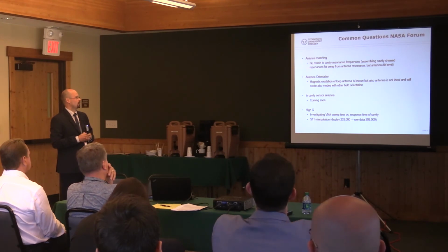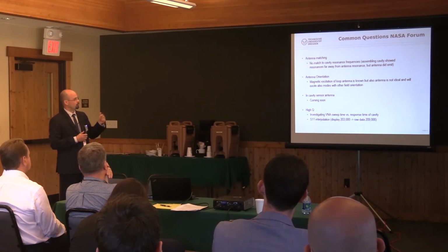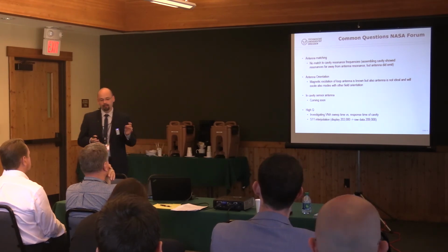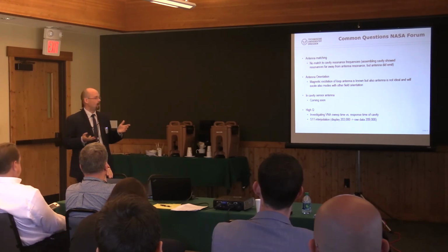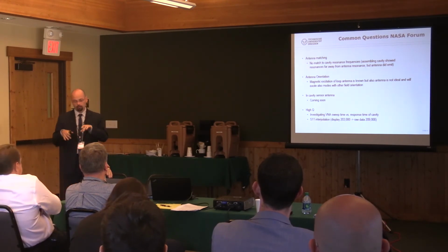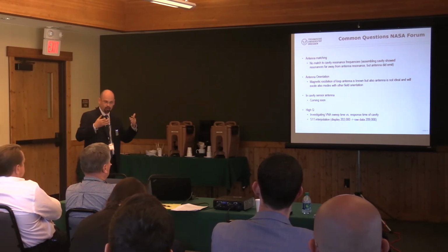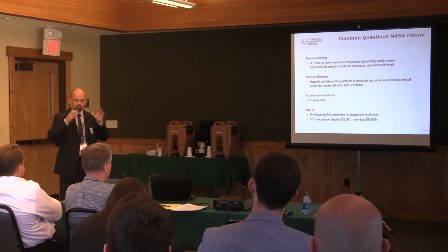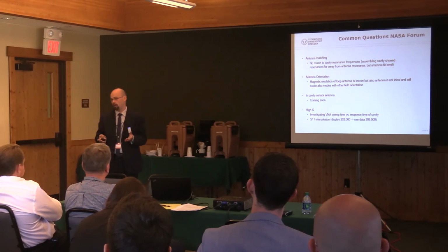Well, in the way of designing my cavity or tuning my cavity, I assembled this cavity while measuring with my vector network analyzer. With an open cavity, so to say with a horn antenna, I saw just the tuned frequency of the antenna, and closing my cavity, assembling the last part, the last flat end cap of this cavity, the resonance frequency of the antenna disappeared, and I just saw the resonance frequencies of the cavity.